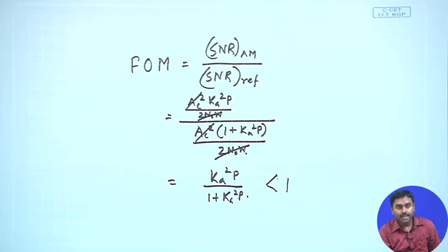That says that after doing this analysis we could understand that DSB-SC is probably more noise resilient compared to AM, because AM, to get a similar signal to noise ratio, will have to launch a huge amount of power, because that carrier power we are putting is wasted and is not really helping in terms of noise cancellation, right. It is not boosting the signal power, which is the actual signal power that will be demodulated. So, because of that we have a degraded signal to noise ratio performance.